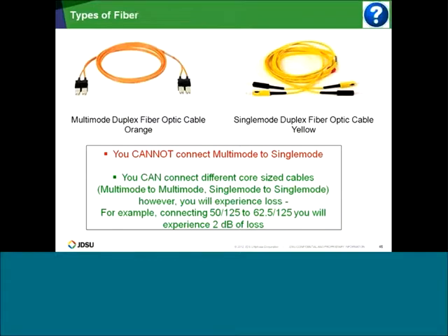So you cannot connect a multi-mode to a single-mode. I've seen some scenarios where you could connect different core size multi-mode cable, however, you might experience some issues. So we always recommend using the proper cable with the proper optics.